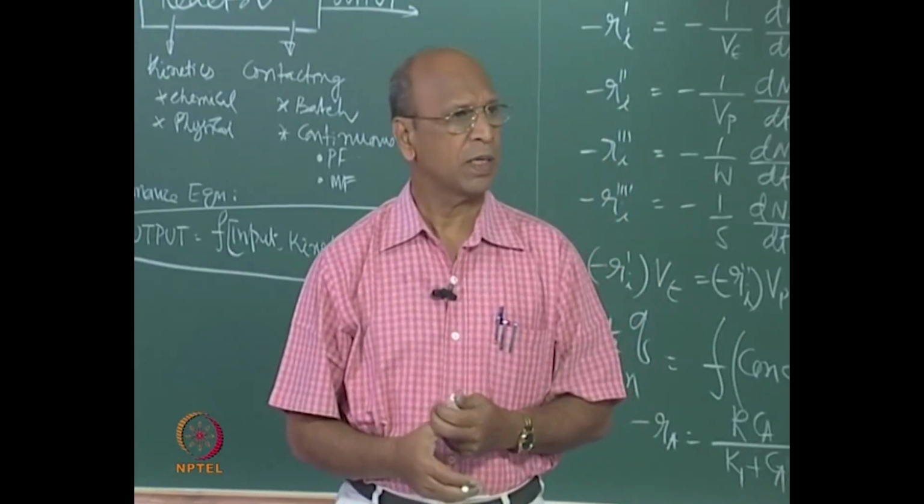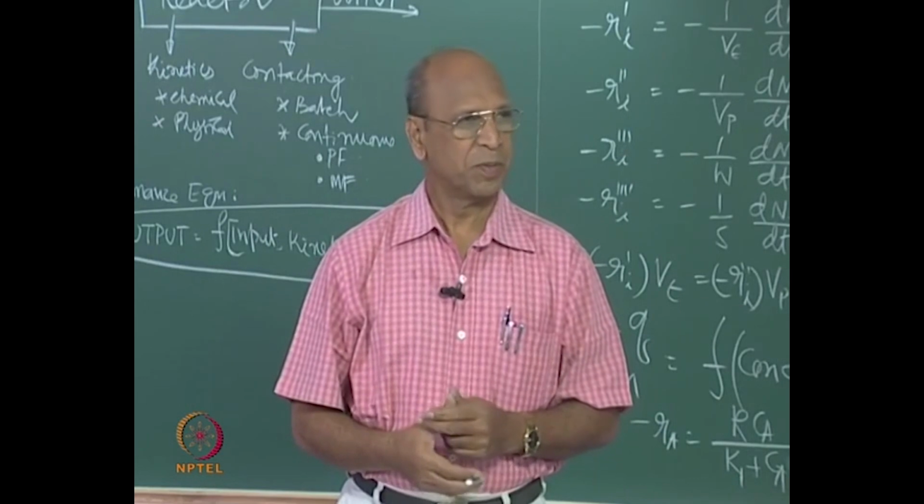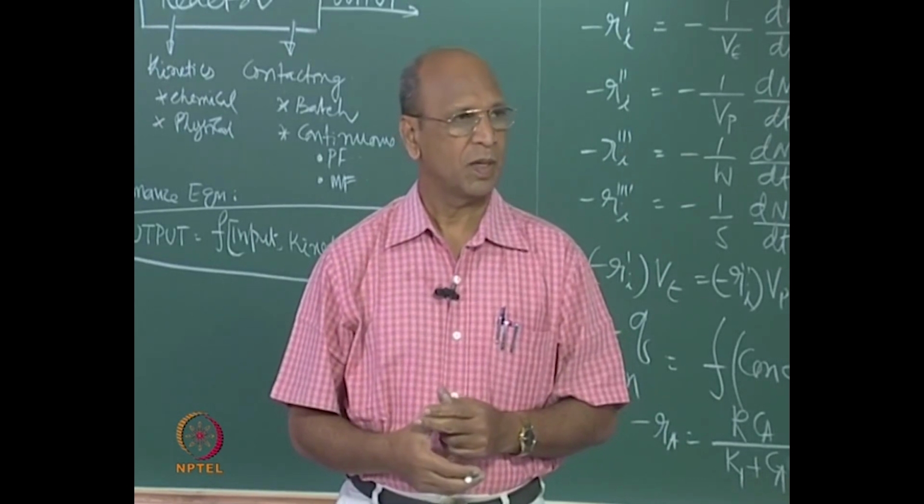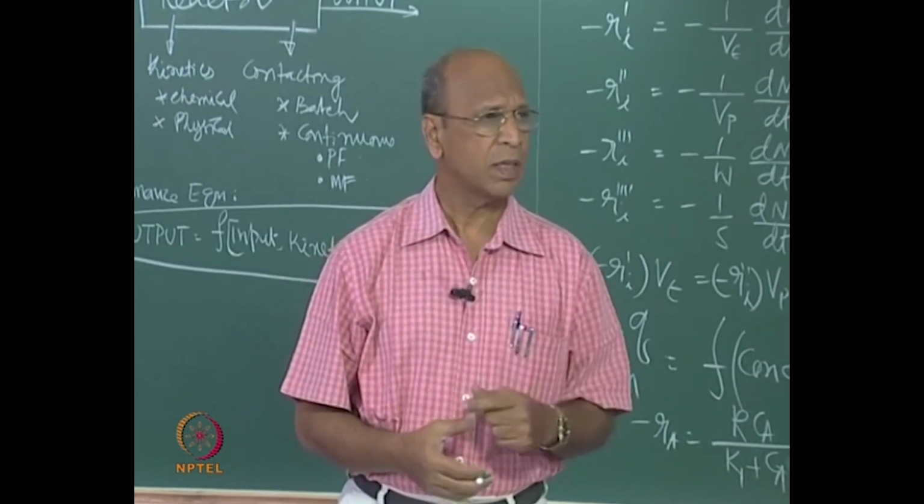Yes, Jahanavi. Mixed flow occupies more volume than plug flow. Again, repeat. For a particular conversion, the mixed flow occupies more volume than plug flow, so we prefer plug flow. For higher conversion. For all reactions.